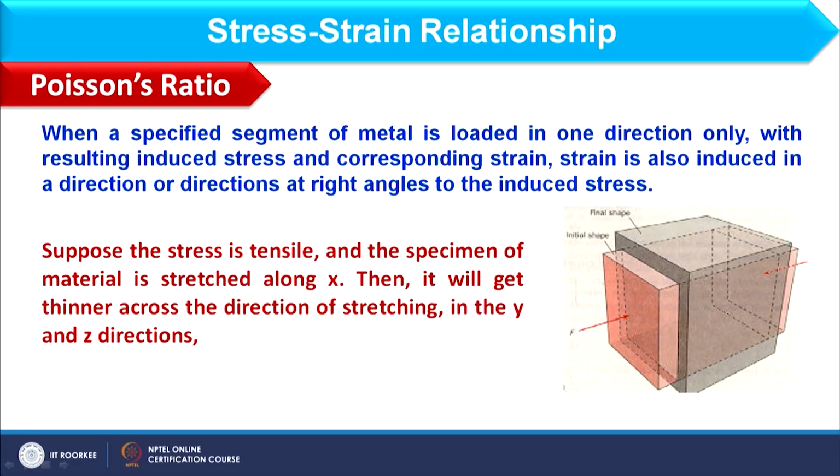And here I have another image where the original shape is this, and from both sides I am compressing it. Stress is applicable in x direction, but it compresses. So, the final length would be a decrement in x direction, however, an increment we can observe in y as well as in z direction. That is the phenomenon when stress is applicable in one direction only.